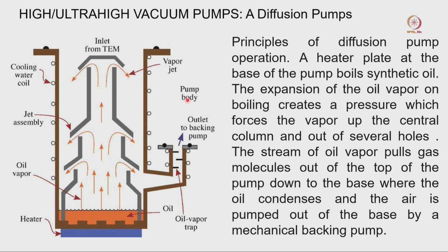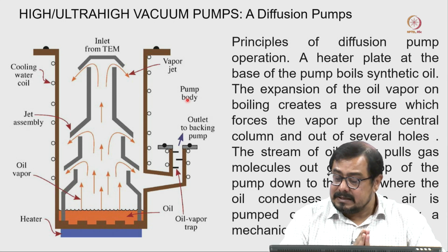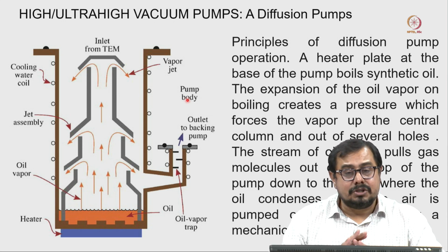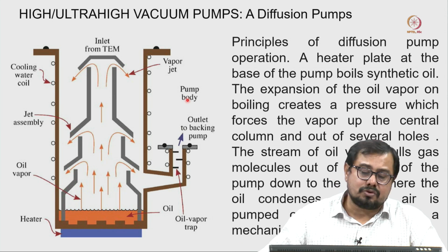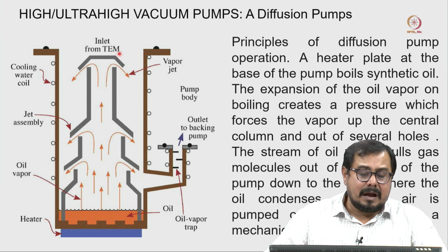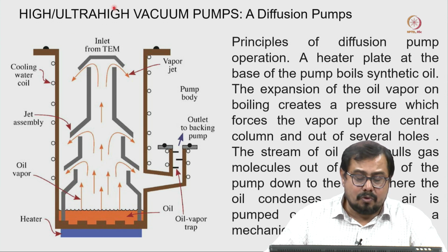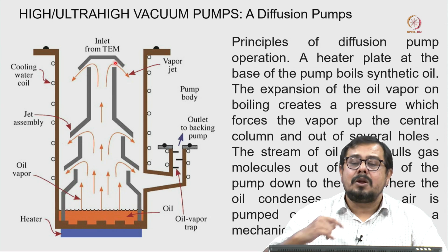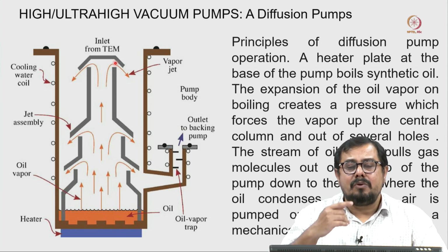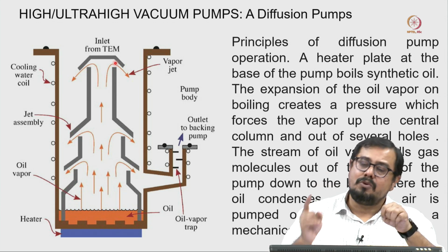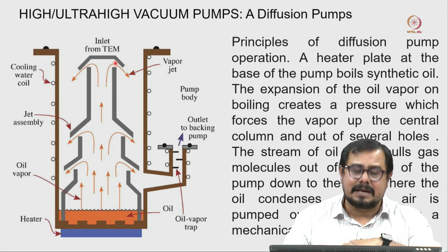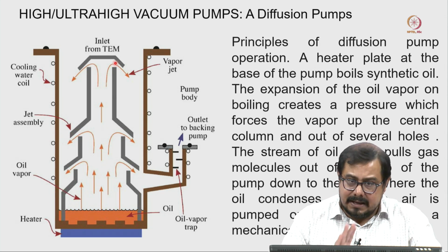Why are we interested in the oil diffusion pump? We are mainly interested because the oil diffusion pump generally gives us a very high vacuum and it is not generating any noise. Why are we worried about noise? Most of the time this inlet from the microscope is directly connected with the microscope, and if this pump generates noise constantly, this mechanical noise, this vibration, will transfer to our images, it will go to the detector and our data quality will be really bad.